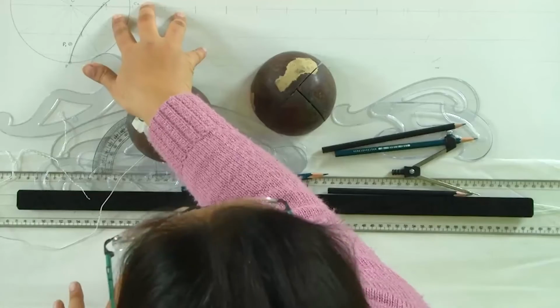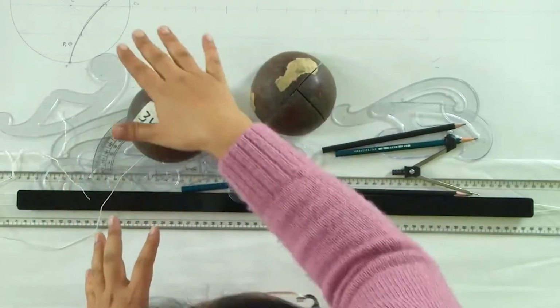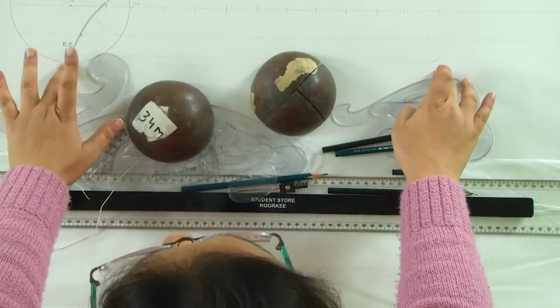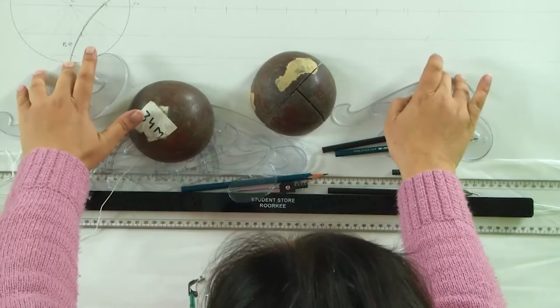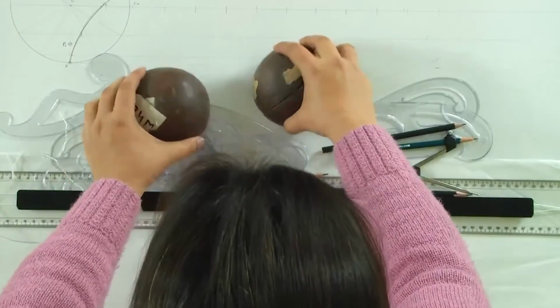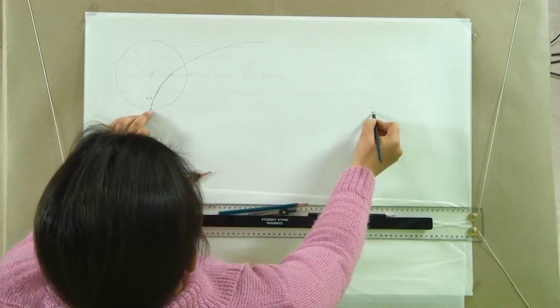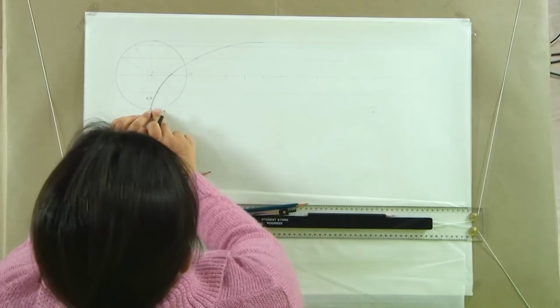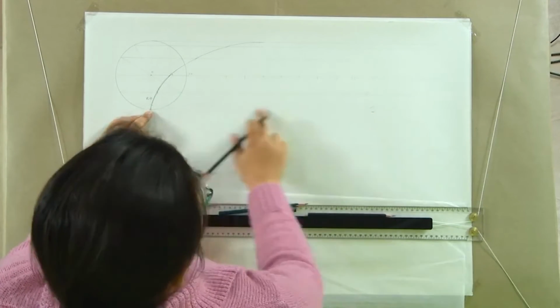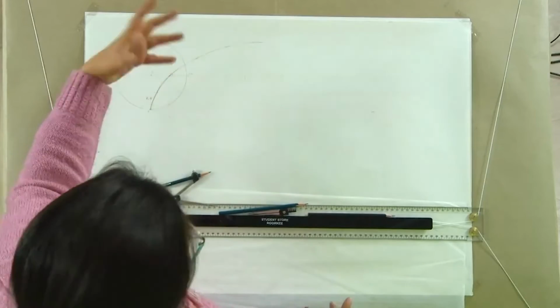Let us quickly see within this sheet how to draw an involute of the circle, because we would need to follow almost the same process here. So, for drawing the involute of a circle, we will again take a line equal to the length of the circumference of the circle, and we divide it into 12 equal parts, any number of parts.